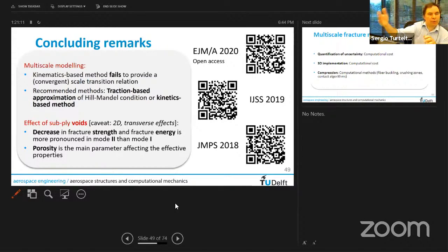That's why you need to do this convergence analysis, in the sense that you take one domain and then you start to make it bigger and bigger. And every time you have a bigger domain, you compute the effective properties, and you check that at some point they don't change anymore. So it is part of the output. You don't know a priori the properties of the RVE. In fact, you don't even know if your microscopic volume is an RVE to begin with. You need to establish that.